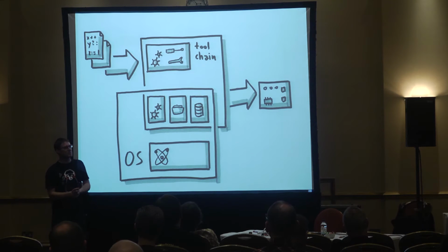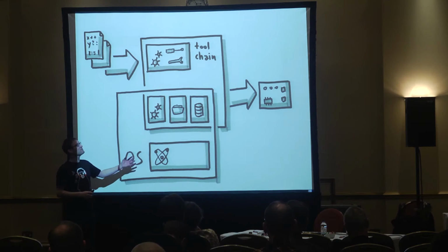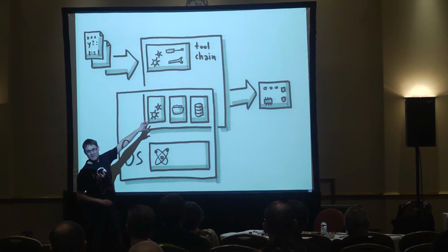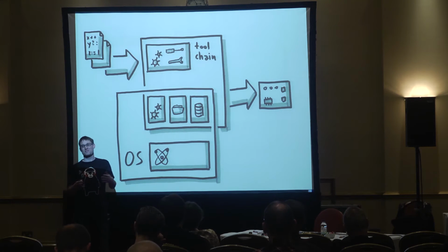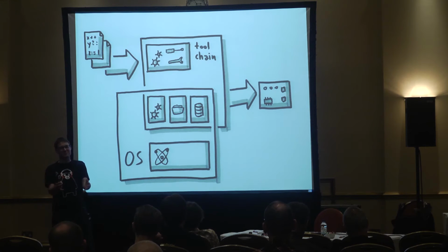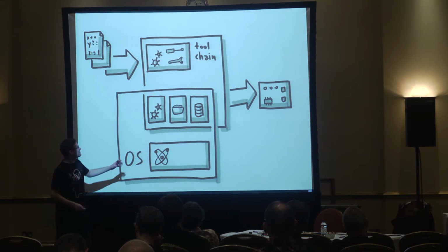Also, the toolchains are one problem because they're not so simple. Sometimes you have a compiler from one vendor, an operating system from another vendor, and maybe even an IDE that needs to operate with the compiler and with the operating system so that you can build your stuff. Even if you do C# on Windows, it's not that different: you need the runtime for .NET, you have dependencies on the operating system, but there you just use Visual Studio and it's already configured because it's homogeneous. You're not going to develop Windows C# applications on some other machine. But in embedded, often these components are from different vendors and they somehow need to match together.